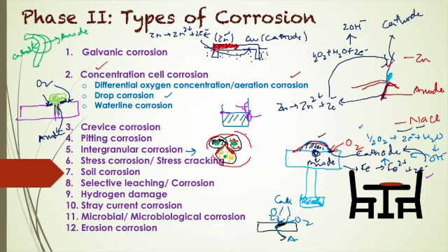Similar processes occur in other alloy systems also, like for example aluminium, iron, cobalt and chromium and other elements which are removed from their alloys. But dezincification is very prevalent in condenser tubes which are made of brass, where zinc gets removed from it, when seawater is used as condenser water.